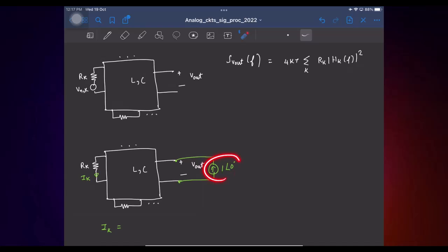You know that if you apply a sinusoidal excitation to an LTI network, the transfer function from this source to the output is some hk, and the transfer function from the current source here to the current here is also hk. So we are applying a current with an amplitude 1, phase 0. You measure the amplitude and phase, that will just be hk. It is for exponential signal. For an LTI also it holds good, right?